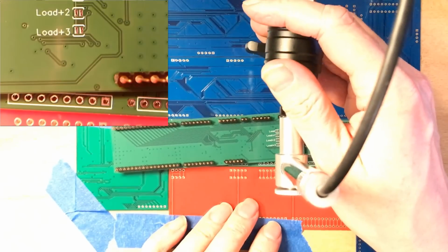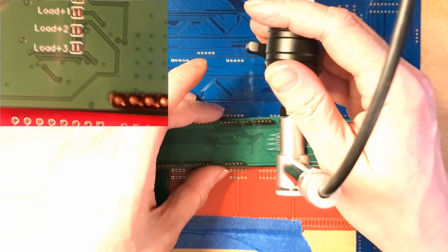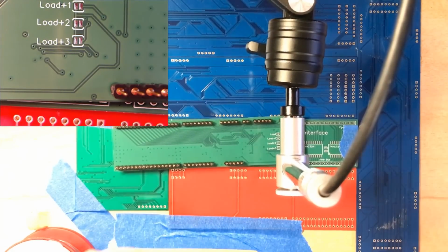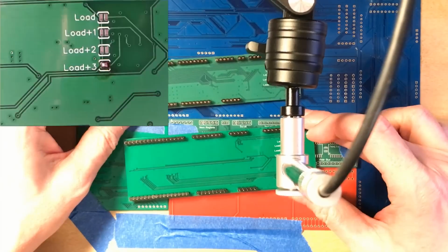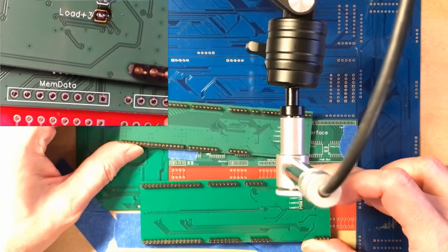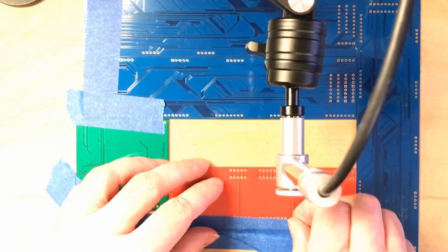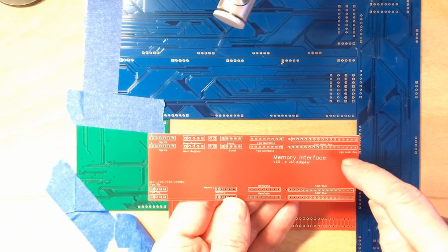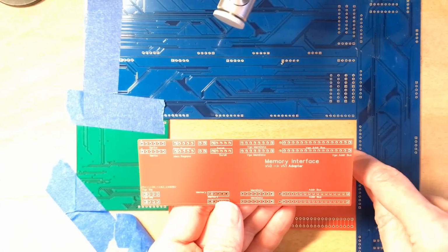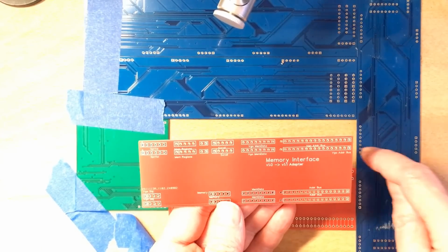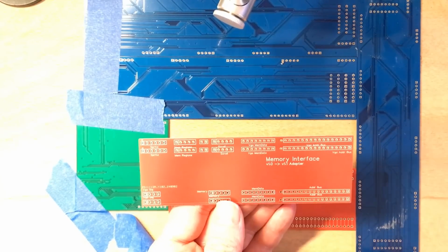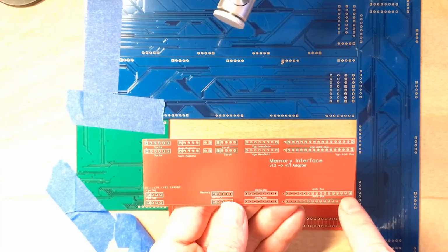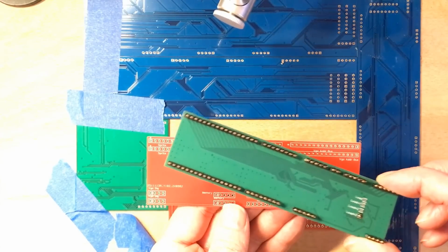Also on the back is this jumper that controls the memory timing. I could probably have just hardwired that because we know what works from the previous version. That's just exactly the same setting as we put on the old one. Now, crucially here, the outer set of holes should be downward pins that are going to plug into the old sockets on the backplane. Obviously I will do a new backplane that uses the correct layout. And then the inner track are female headers for this to plug into.